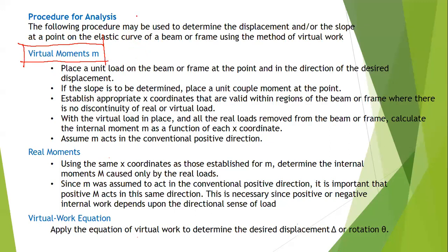If we wanted to determine the rotation, then at that particular point, we will apply a unit moment. Second, we also need to set up our real moments M. So we are going to create expressions for moments at different sections of our beam.